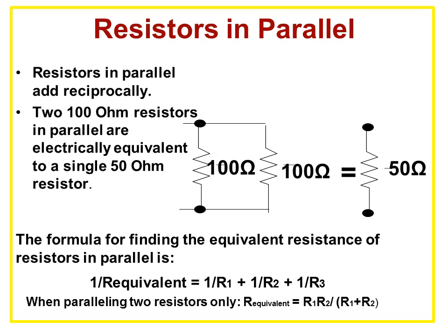Resistors in parallel add reciprocally. 2 100 ohm resistors in parallel are equivalently equal to a single 50 ohm resistor. Because they provide 2 paths, the resistance seen by the source is lowered, not increased. The formula for finding the equivalent resistance of resistors in parallel is 1 divided by the equivalent resistor is equal to the sum of the reciprocals of the resistances of the resistors in parallel.